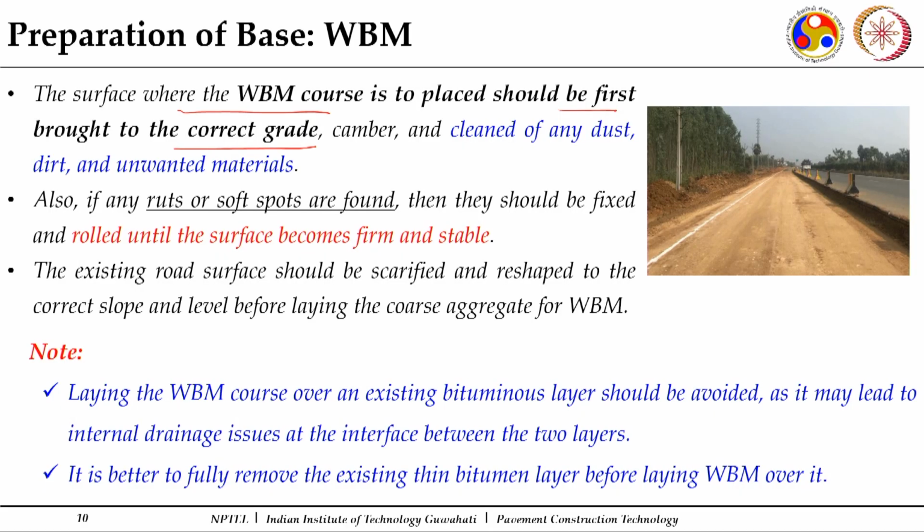So, in that case, for any reason, if any movement of vehicle, any growth of vegetation, or any movement of construction vehicle has damaged the existing surface, it has to be rectified, corrected to the grade and camber and cleaned of any dust, dirt, unwanted materials.